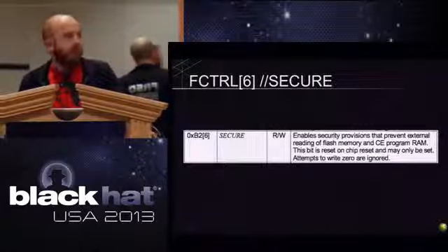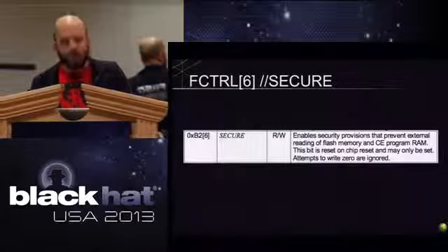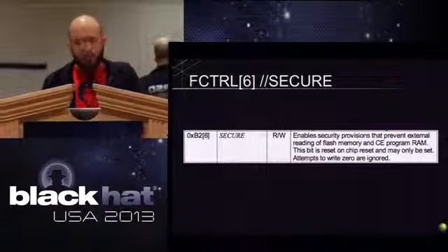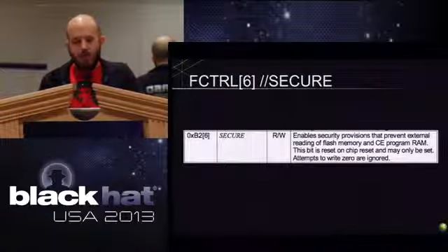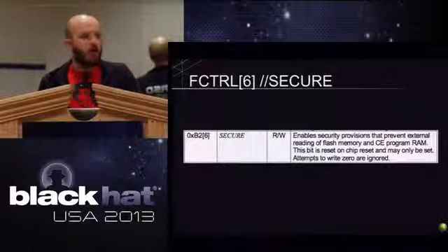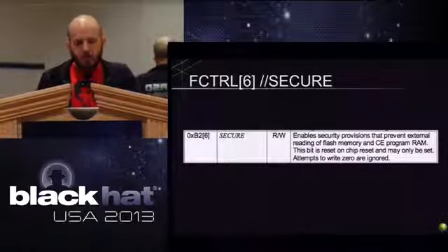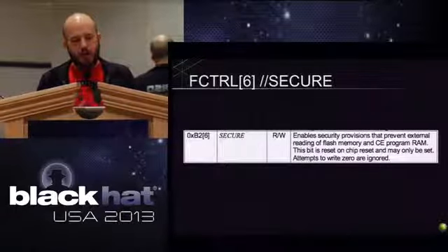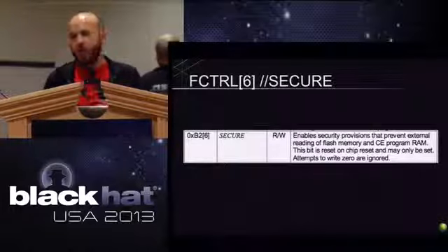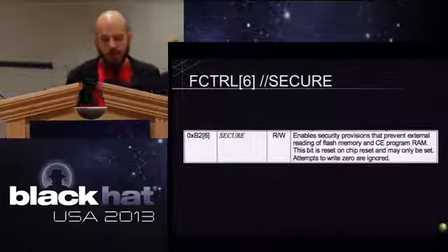All right, so let's talk about bypasses for some of the things we've talked about. Okay, so the secure bit, right? This is the thing that says, let's prevent the ability to use the debugging interface. So this says, I'm not going to let you externally read flash memory. I'm not going to let you light up the debugging interface.